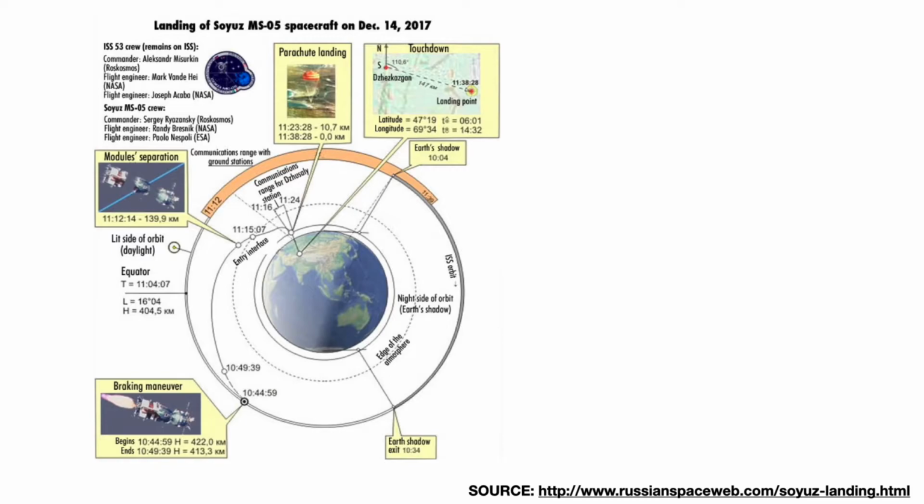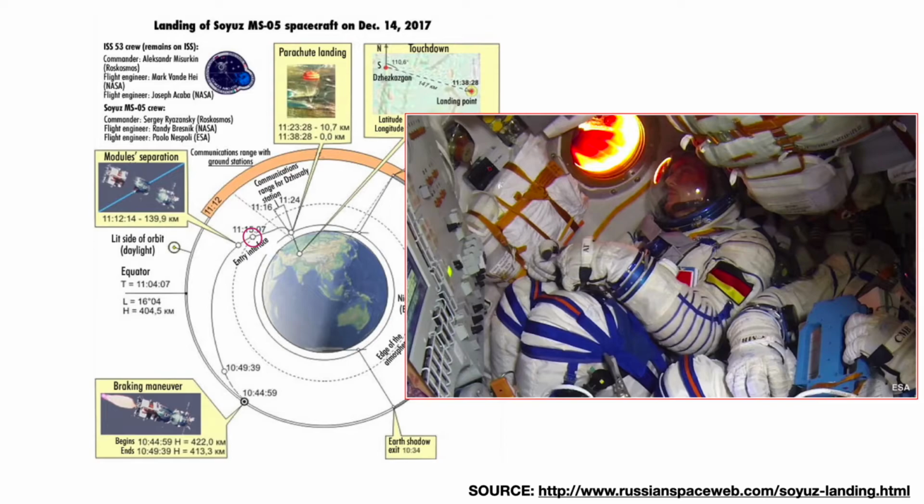For example, here is a landing sequence for the Soyuz spacecraft. It begins with a deorbit burn, in which the spacecraft changes its velocity by 128 meters per second. Following the deorbit burn, the spacecraft cruises for a while, as the lowest point in the trajectory happens on the other side of the Earth. Right before the spacecraft reaches the upper atmosphere, the descent module of the Soyuz splits away from the habitation module and the service module.